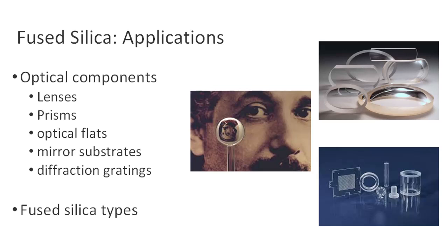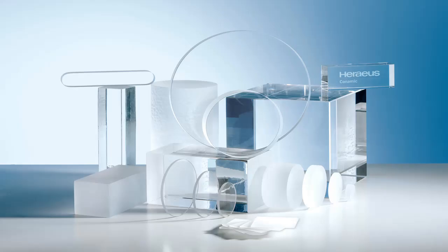Fused quartz, fused silica, or quartz glass is a type of glass that consists almost entirely of silica, SiO2, in its amorphous or non-crystalline form. Unlike other commercial glasses, which are made by adding various ingredients to modify their optical and physical properties, such as lowering the melting temperature, fused silica is a pure form of silica. This purity gives fused silica its distinctive high working and melting temperatures, which makes it less suitable for many common applications where lower melting points are preferred.